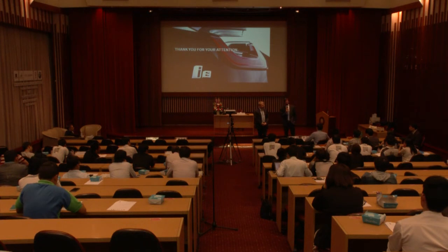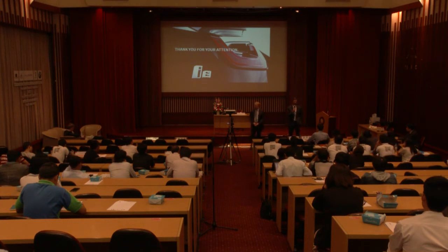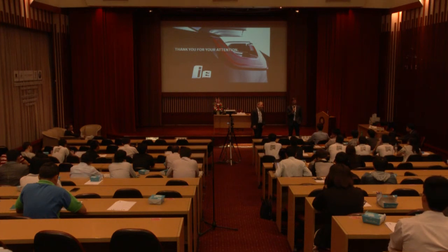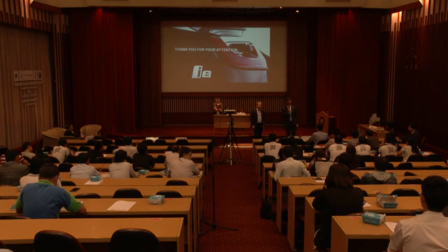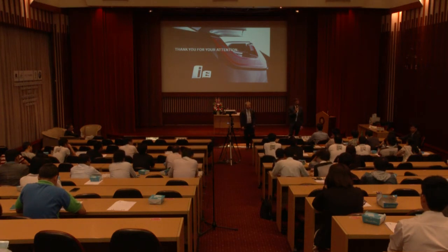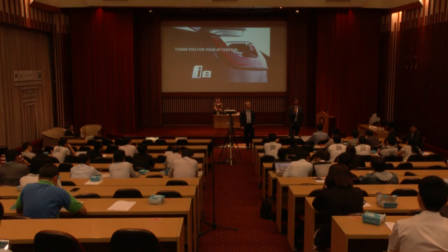You have some functions in milliseconds and some others. Yeah, we have functionality which calculates the sensor values at the microsecond level, and we have functionalities which run on a 100 millisecond cycle. So there we have not only one cycle, but a kind of multitasking operating system which allows those multitasking parts, with a 100 millisecond task and a 50 millisecond task and so on.